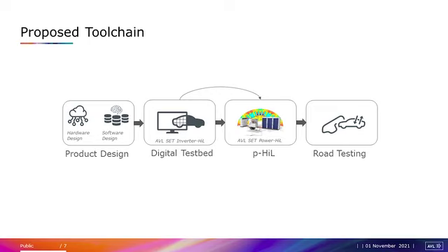So what you learn there is not only how the signal part of your inverter will behave on Power HIL. You can also start some sort of rudimentary calibration of your controller parameters. Then you proceed on Power HIL, you calibrate your sensors, you test the performance of your inverter, and you can proceed to road testing directly.